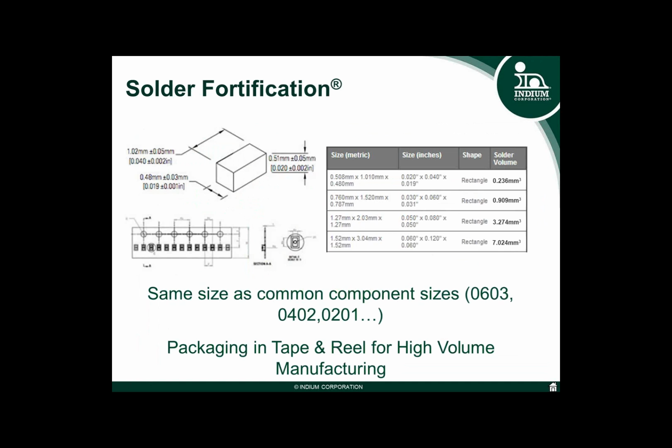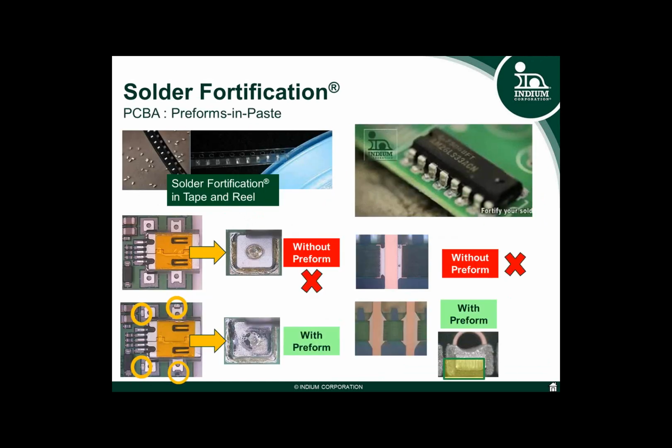And they are what I would consider, as an engineer, a get out of jail free card, especially if you were a contractor and you needed to meet a defined solder volume and the stencil just wasn't of the right geometry, so you didn't have the same solder paste, but you could then add a solder here. We call them fortifications, solder bricks, added to the application to increase that volume.